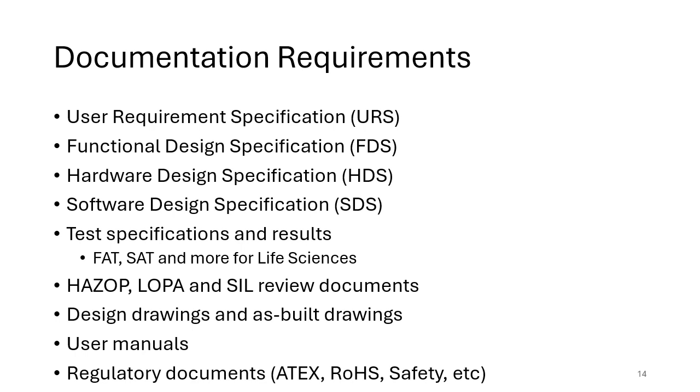And it may also include details about testing. It might include details about panel protection and capabilities, and even down to the color and thickness of paint and so on, but normally at the very high user level. There may be a functional design specification. The functional design specification is the next level document that describes the function of the system and how it will operate. So this might include details of sequences, it might include more details of the particular interfaces, and it might even go into some details of how the user interface and the user experience might look.